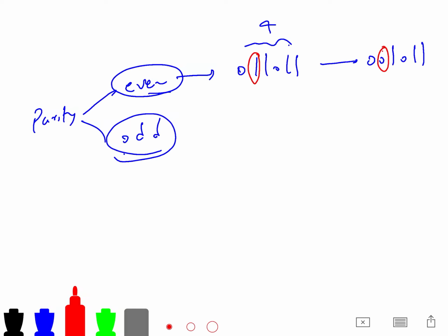We have missed this one. But we don't have any problem. So here it is 3. So we had 4, now we get 3. So we need a retransmission request to be sent. So you get the idea, because it is an even parity. You cannot expect the sum of ones to be odd if noise doesn't affect it. So now you may guess that, oh,